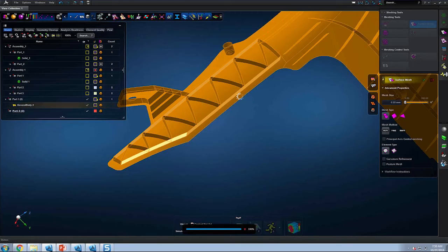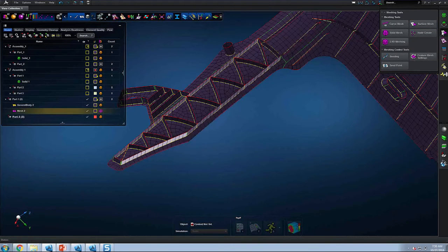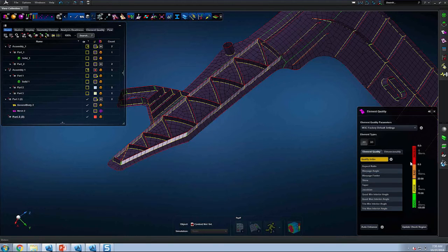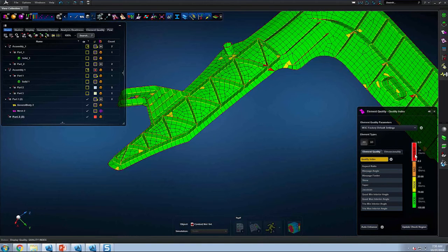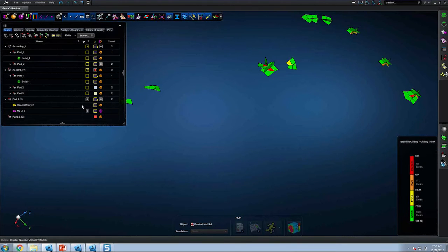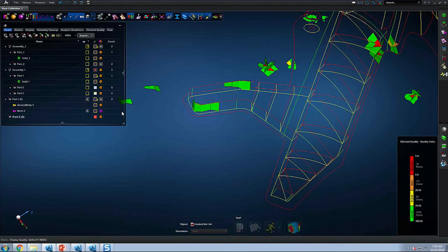And the one thing I want to show now is the ability to do two things. One, I can detect problems with the mesh. And here what I'll do now is I'll just isolate and view elements in the model that are so distorted that when we perform an analysis, we'll get a failure of some sort.